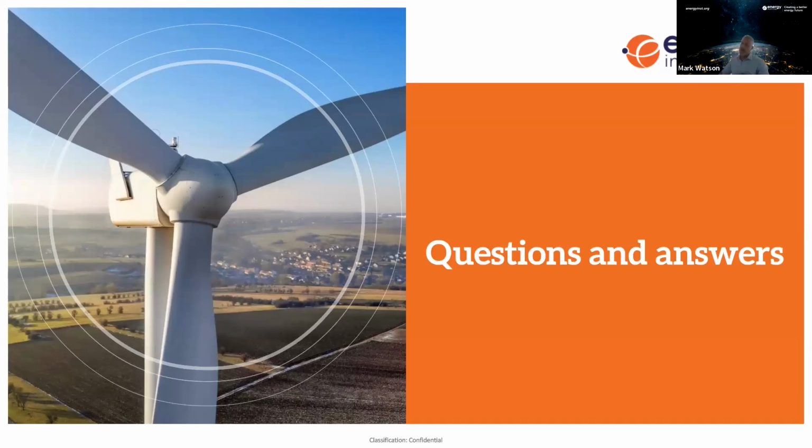Yeah, and again, it's about understanding the expectations from the HV contractor, as well as what's documented under this process around the wind turbine safety rules. If the HV contractor is purely there to put isolations in for the work to be done on the other side of the boundary under the wind turbine safety rules, they might choose that they don't need to issue a safety document.